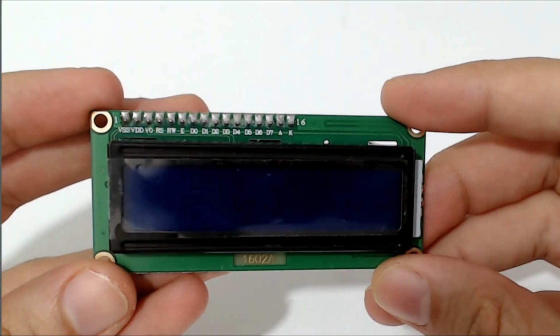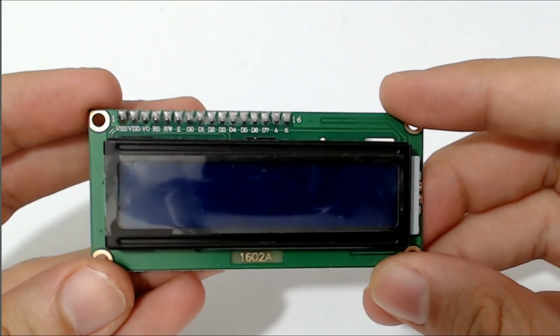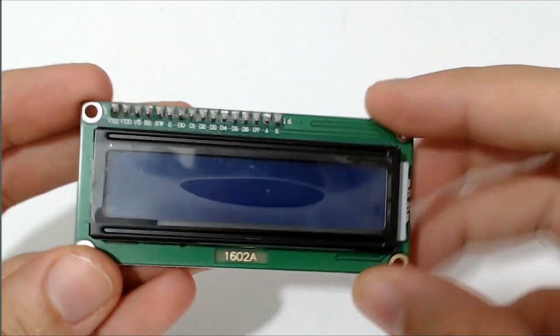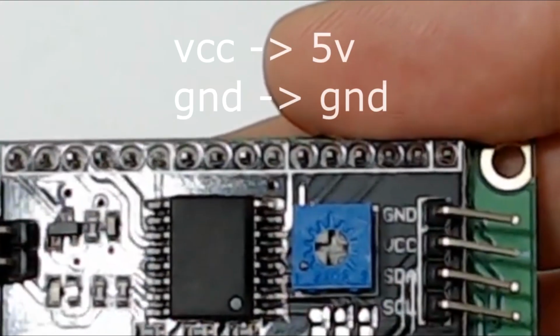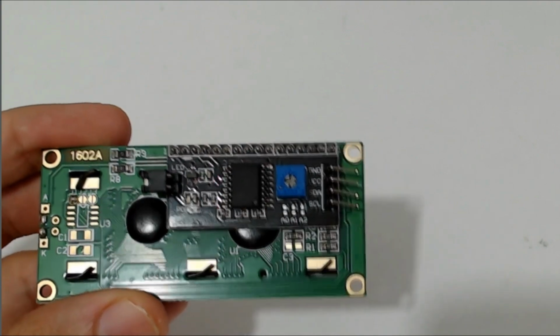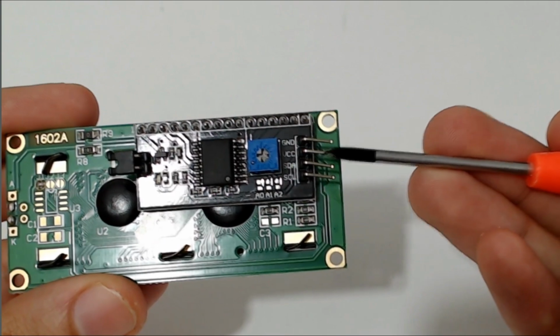Our LCD screen consists of 2 rows and 16 columns. Also, we need to use 4 different lines to code our LCD screen. 2 of these lines are power lines, that is the GND and 5V pins. The other 2 lines are the I2C line, signal pins on these lines.